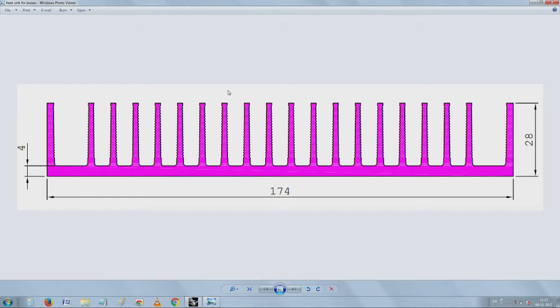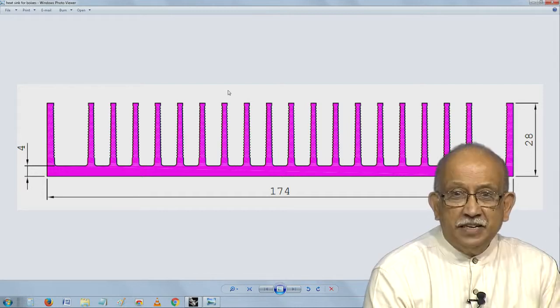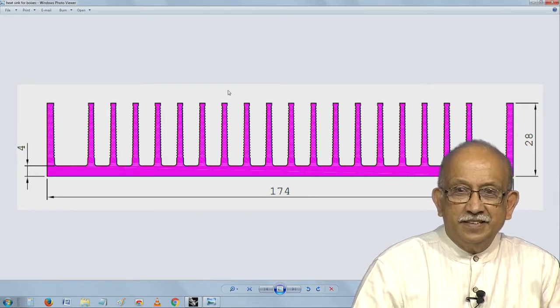having estimated what is the loss in your equipment, meaning if it is maybe a 10 kilowatt device, and then you expect the steady state losses at the appropriate loads which we know. Partial load, it is very inefficient, overload is inefficient. At the correct load, the efficiency will be optimal, or probably the best efficiency you can get is about 90%. So, 10% losses will be there. Now, based on this 10% losses, we can